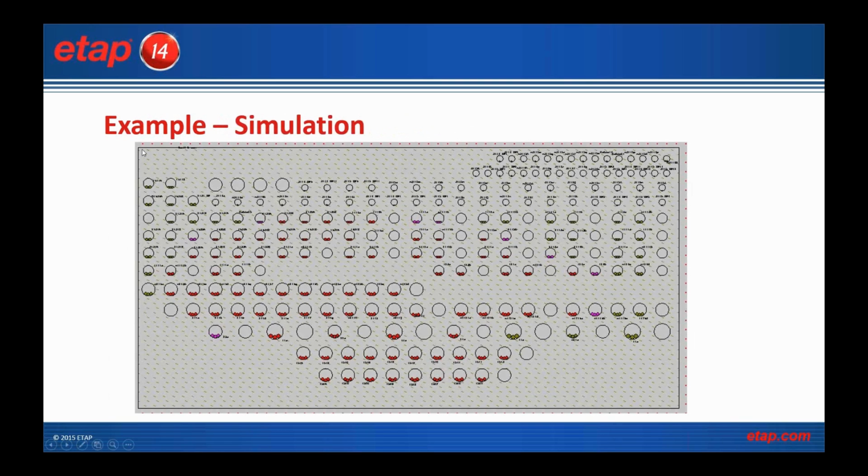For example, the y-axis by x-axis ratios typically are 2 or 3, and should not exceed those ratios, otherwise the equations are no longer valid. But those are the cases where the program warns you when the equations may not be valid based on the type of raceway that you're building, very similar to our ground grid system. But there's no limit to the number of conduits or the number of conductors. You can add as many as you like.